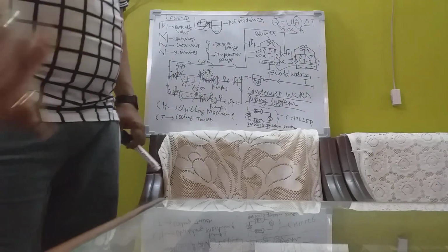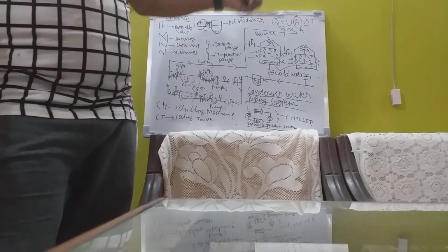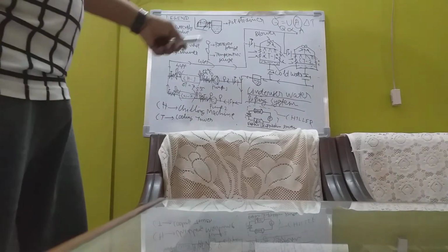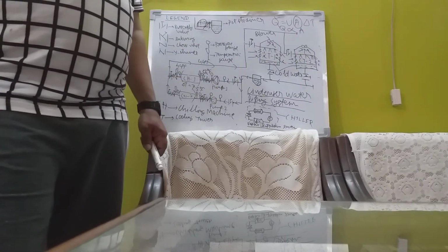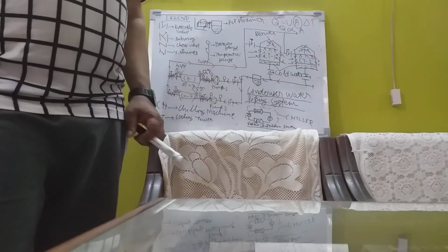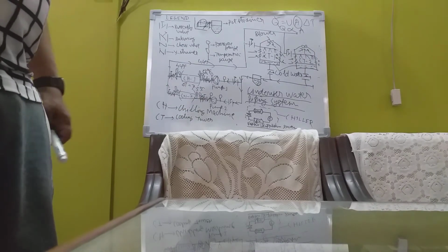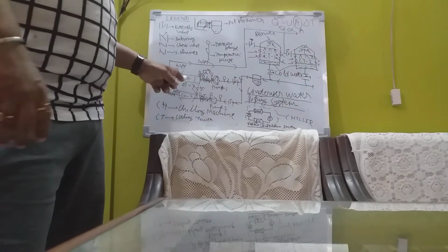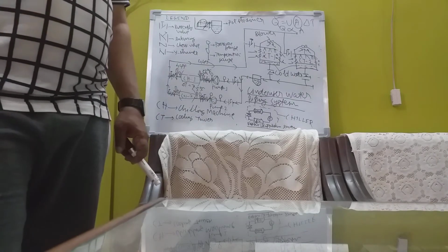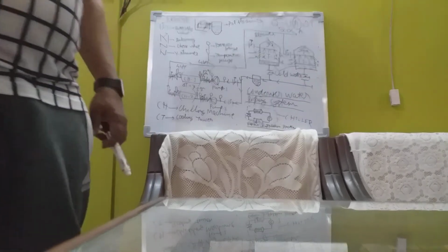But your operating cost decreases. That increases your installation cost, but operating cost decreases. That's the advantage of using the water cooling system. And when you are using the water cooling system, the water gets better cooled. And water being better cooled than air cools the condenser better, and the performance of the chilling machine increases. This is a great advantage with the condenser water system.